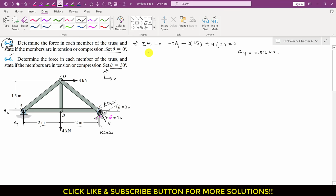Now if we apply the summation of moment about point A equals to 0, right? Again we will assume that the counterclockwise moment is positive. So now as we can see that this sine component is passing through that point A, right? And this r cos of 30, this component is producing the counterclockwise moment about that point A. So I will write plus r cos of 30 degrees, and the perpendicular distance of this component from that point A is again 4. So I will multiply this with 4.